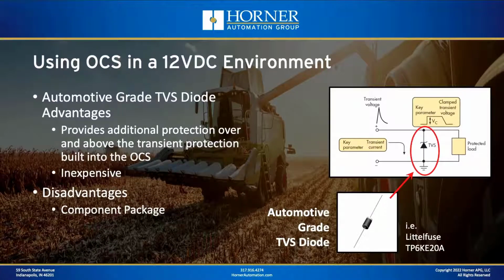So of course the advantages are the additional protection that you receive from a very inexpensive component. We're talking about a sub $1 component. Of course the disadvantage is this is an electronic component in a leaded package, which takes a little bit of care to be installed in a typical control enclosure type application, but it's certainly not that difficult. You just need to take some care in the install based on the package. So that is how you can solve load dump by adding an automotive grade TVS diode to your system.